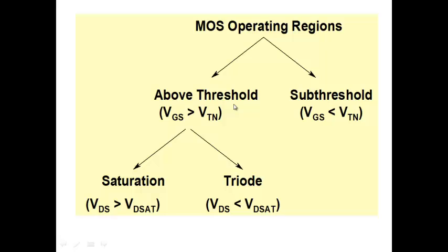For our analog circuits course, the most important region is the saturation region. For all the amplifiers, I will bias my MOSFET in this region, and then my MOSFET becomes capable of amplification. So we need a model for the MOSFET in the saturation region, a small signal model. The MOSFET has capacitances, so we have to understand all of that and put it together to build a small signal model for the MOSFET. That will be the topic for the next 2 lectures.